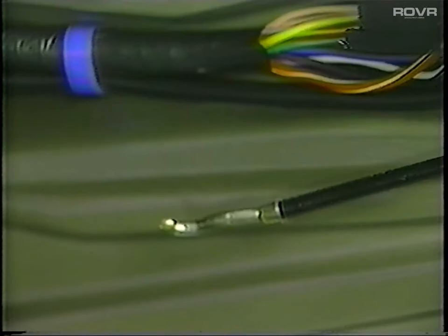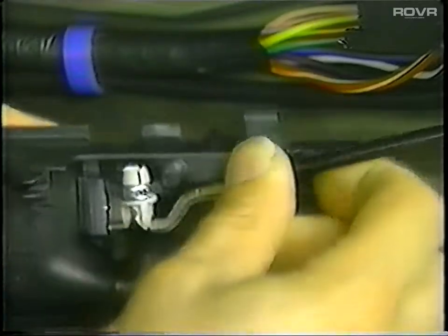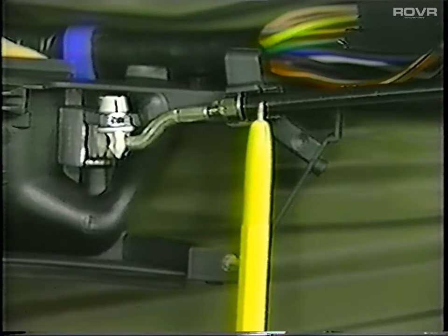You will also notice that the inner door latch is cable operated. On reassembly, be sure to insert the cable collar in the correct slot in the keeper. It can easily be installed in the rear slot, which is incorrect, and the door latch will not operate properly.